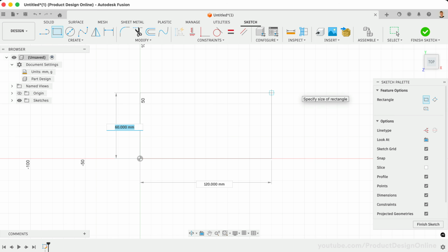Use the Tab key to ensure you're on the width dimension. Type out 15.8 millimeters for the width of the toy block. Press the Tab key again to lock the dimension. Then type 31.8 millimeters for the length. Click any of the 4 quadrants to place the rectangle. For this specific design, the direction does not matter.